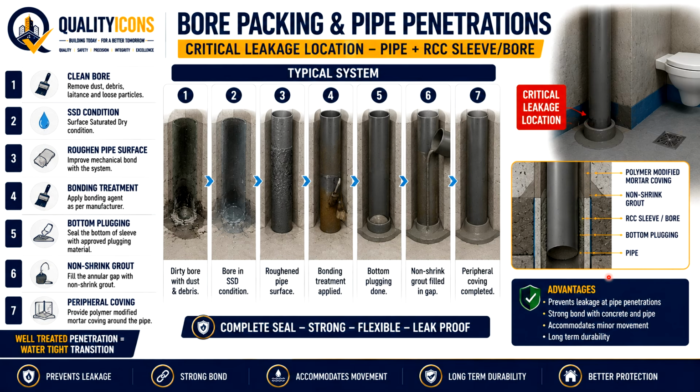The bore should first be cleaned properly and brought to the required SSD condition. SSD means surface saturated dry condition. The pipe surface should be suitably roughened and the specified bonding treatment applied.